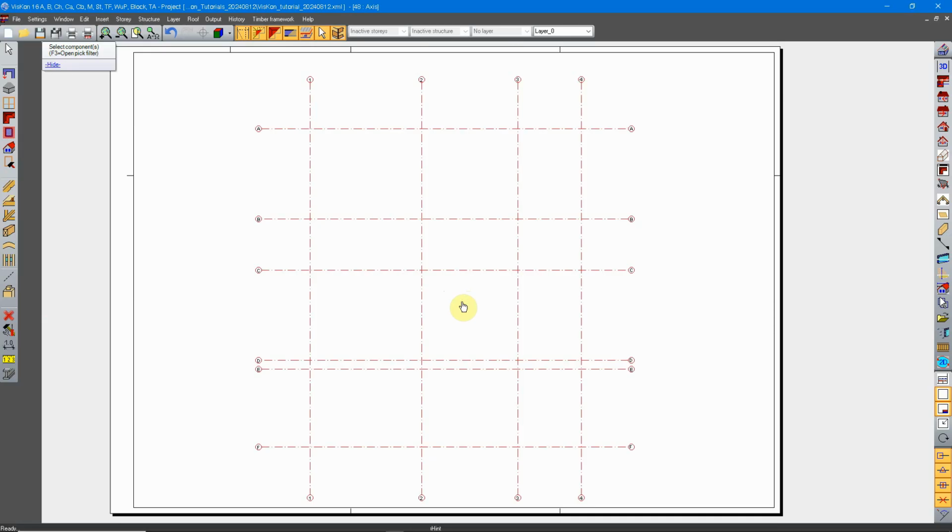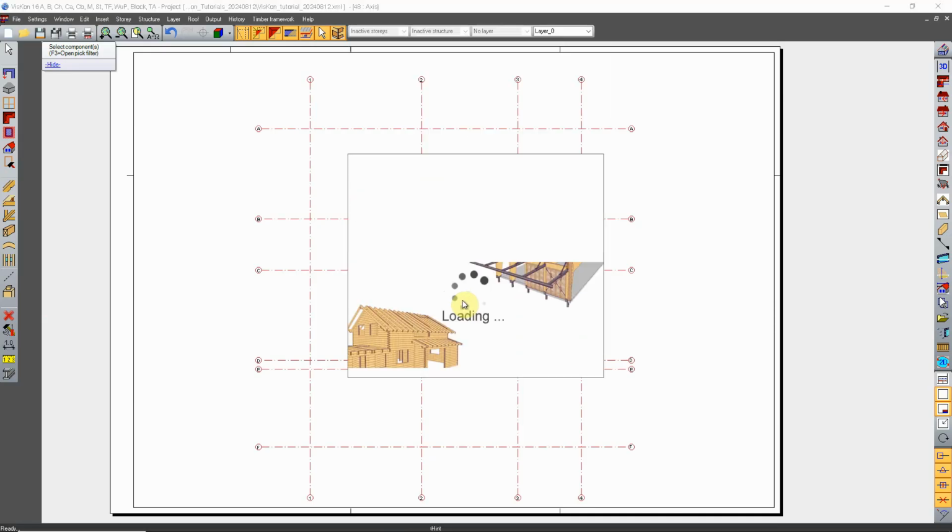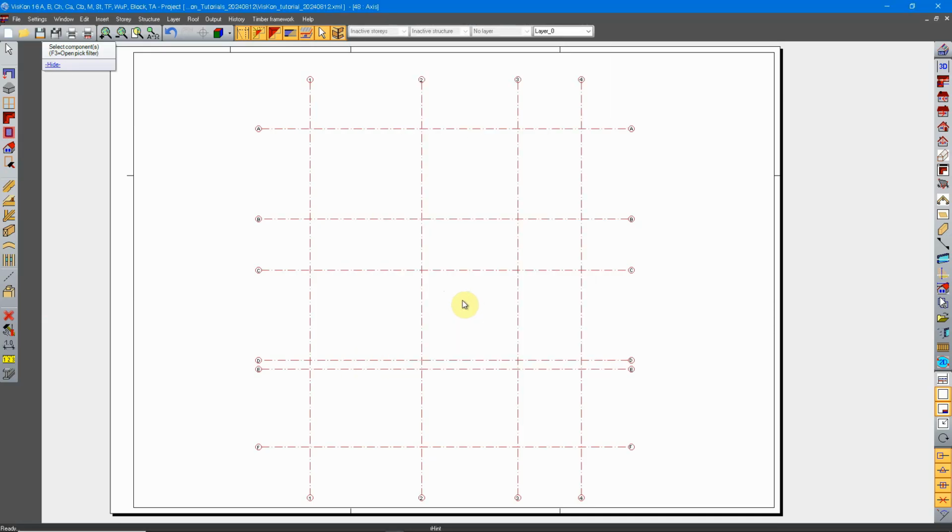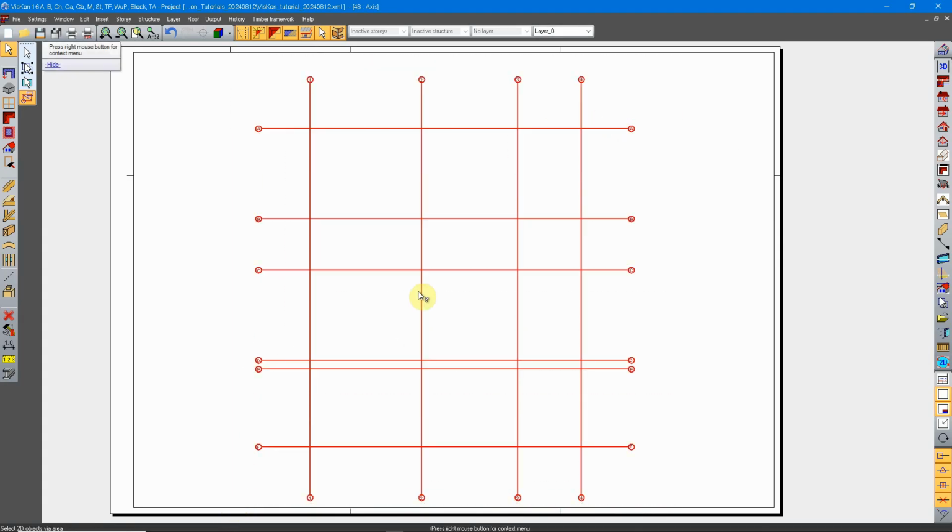And there you have it. We have the full axis system here drawn in 2D. Now, if you want to use it on your other drawings, you just have to select with the 2D object selection method. Select all your lines and texts and other objects.